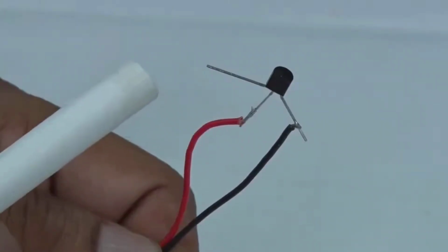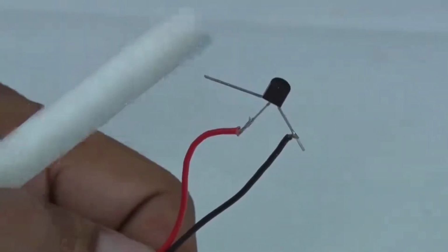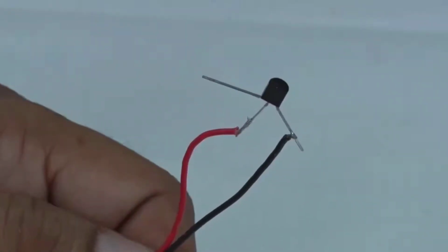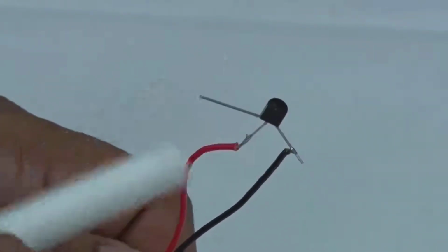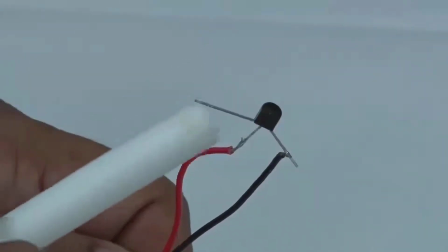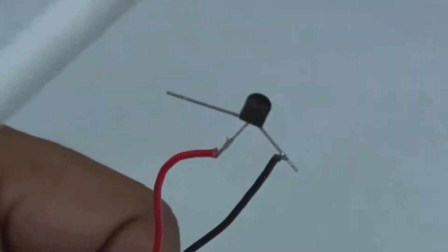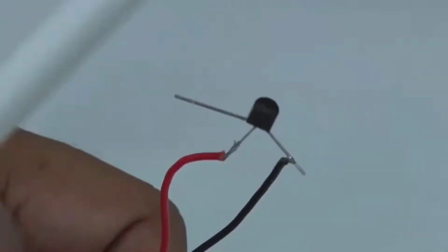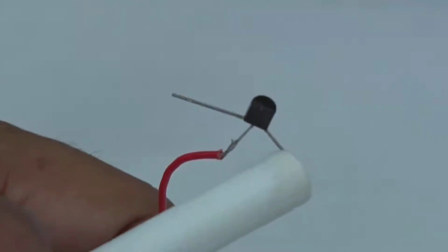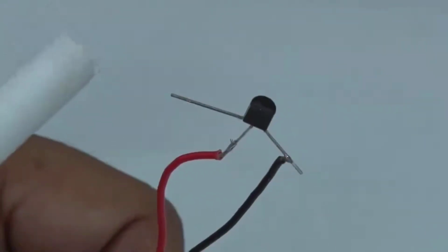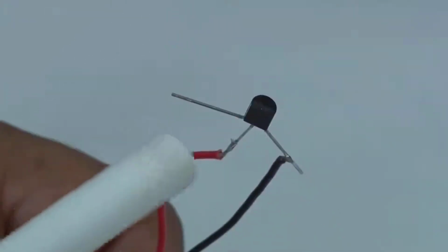You also have high power transistors. This is a low power one, used for small currents, and then you have other kinds of transistors where the casing is metallic, a full cylindrical type of thing, and from the bottom there are 3 leads coming out, and on the circular cross section at the top there is a notch from which people find which is the first lead, second lead and third lead, and then the data sheet will say which is emitter, which is collector, and which is base.